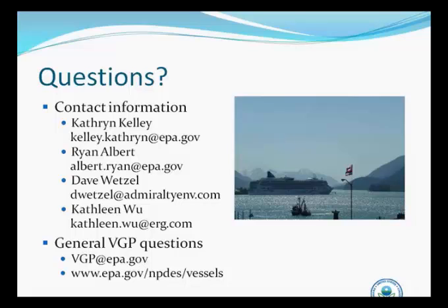What happens when the lab technician exceeds the holding time because they didn't get the samples back to the lab in time, i.e. had other sampling jobs on the way? There would be a quality qualifier that was not under the control of the client or the owner. So Kathleen? I think in that situation, and it's assuming it's the fault of the lab, you've got two options. One is to have them run the sample as is, and in their analysis report, it would note that this analysis was run, this is the result, but it was done exceeding the hold time.